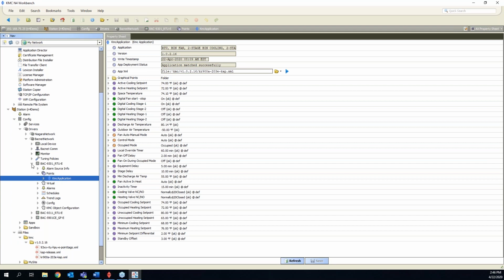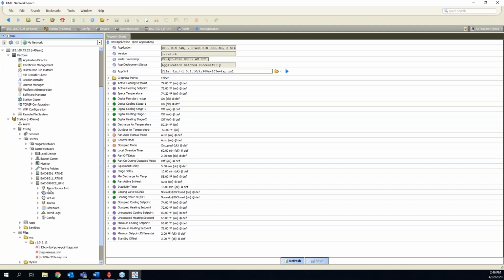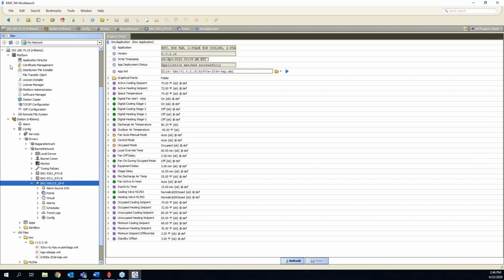And if you're using a standard BACnet device, or it's a job using our controllers and somebody deployed it as a standard BACnet device, and you're coming in after the fact and you just want to access the embedded programming, you still can, if the JACE has the modules.